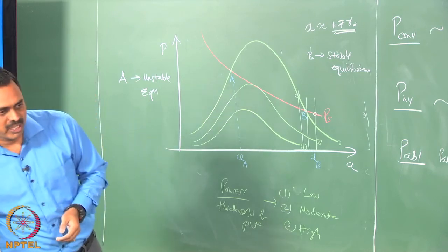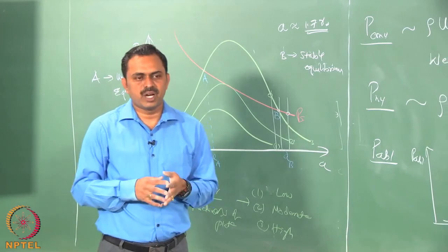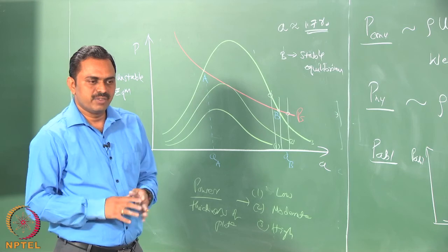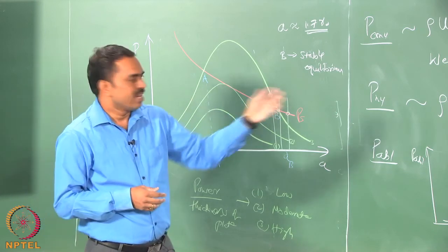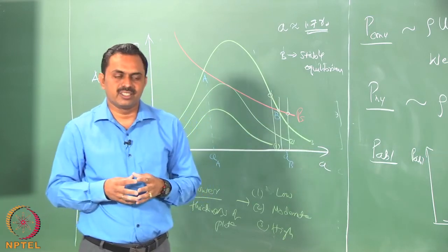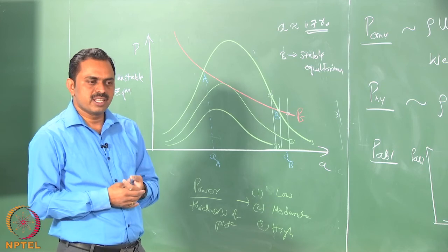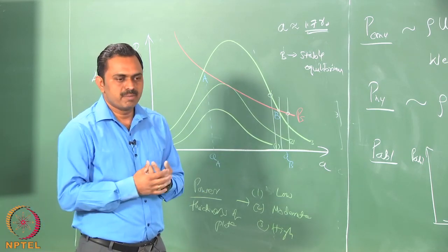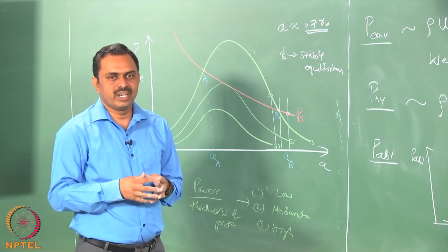So with this we close this lesson on keyhole mode welding. I hope it is now clear to you how the transition from conduction to keyhole mode happens. It is important to keep in mind that these are possible only in the right hand spectrum of the heat intensity distributions of the various welding processes, and one can take advantage of keyhole mode welding to avoid multiple welding sequences, so that single pass welding is possible.